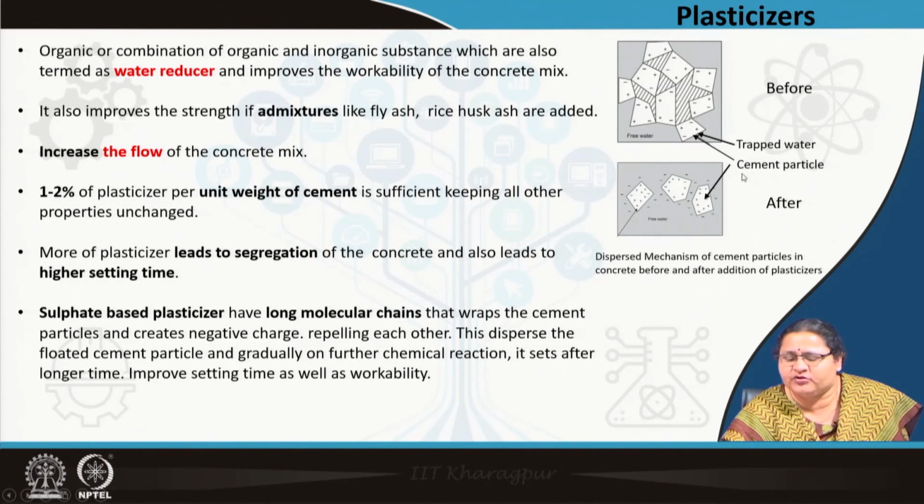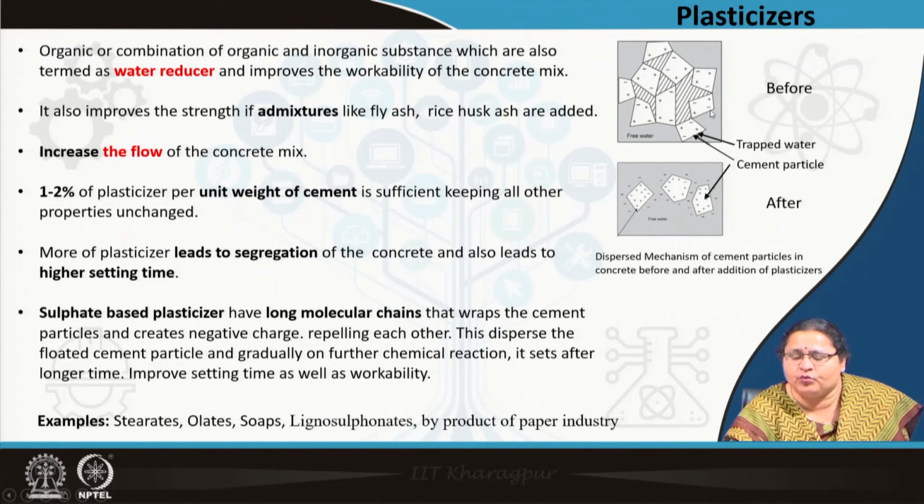So, this is the pictorial representation of the dispersed cement particles in concrete. Before, it was closer and water was trapped in between; now water is free, the cement particles are repelling each other and it is allowing a free flow.